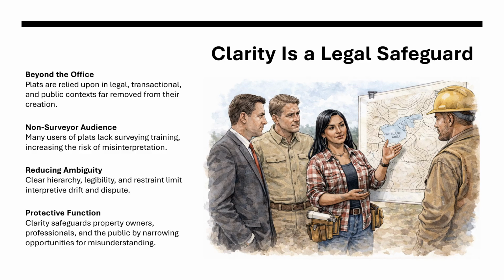A plat is read by more than surveyors. Judges, attorneys, planners, developers, and homeowners rely on these plats without necessarily understanding surveying conventions. The drafter's job is to make the document intelligible without oversimplifying it. Clear hierarchy, legible text, restrained annotation, and deliberate line weight are not cosmetic decisions. These are safeguards against ambiguity, and in legal settings, a clear plat protects everyone involved.